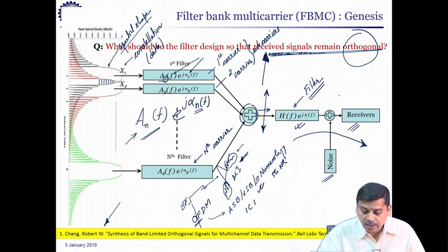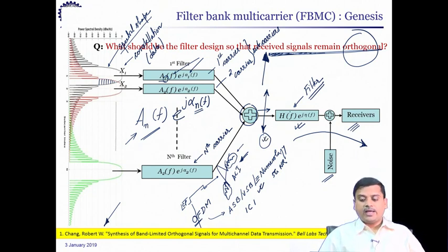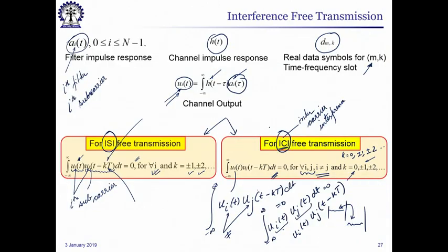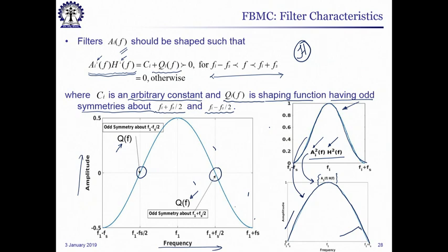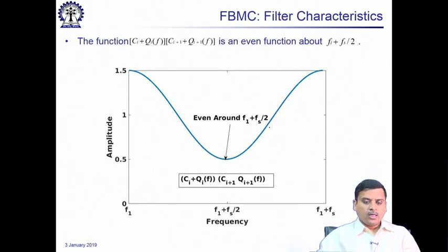Now, if one wants to get back to the situation of finding orthogonality over here, one can simply set the channel to be an ideal filter, and one would get the criteria required at the transmitting end, right. That is as simple. So, this is more general, and it is useful if I know the channel characteristics, and especially useful if the channel is going to remain constant over a certain duration of time. So, there are some more criteria that come up.